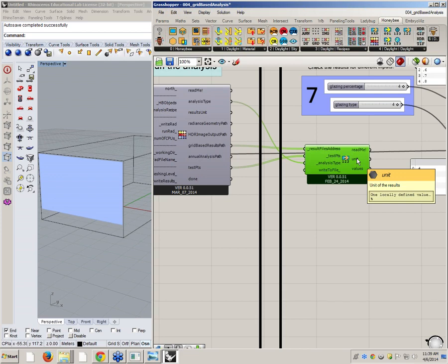So we talked about the cloudiest sky, right? If you imagine the cloudiest sky, you consider 10,000 lux horizontal. 2% of 10,000 is going to be 200. So 5% is going to be 500. Am I right, or am I adding a zero? I think I'm right. It's morning, I can be wrong. But that's the concept.